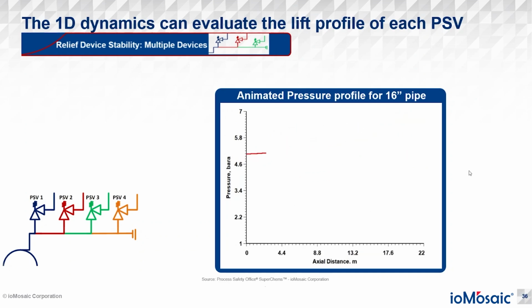So in terms of stability, it's not that great. As I mentioned previously, I chose 16-inch just for this example. So I wanted to say, well, okay, let's say I've got quite a large nozzle. It's a big system, and I do have the opportunity to increase that piping, because let's say I'm reducing from, I don't know, a 30-inch line, 32-inch line, and I reduced down to 16. Just hypotheticals. So I do have room to play around with the diameter there of the piping.